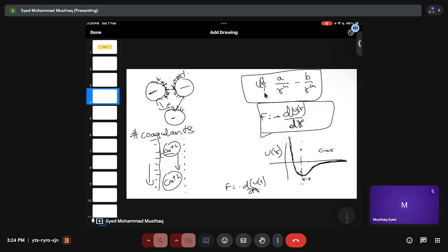So there is this layer up to which they move, and they are very strongly adherent, so when this moves, they also move. But what about the next layer? That layer is not very much attracted to this one. So then there is a shear. That's what happens with fluid flowing on a flat plate, right? When the fluid is moving, the fluid near the surface has zero velocity. That is what happens in a pipe, right? So this is the velocity vector, look.